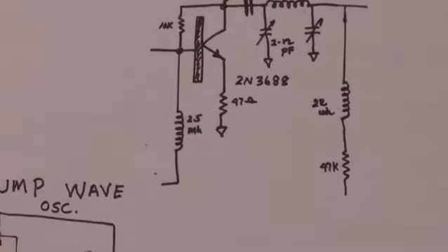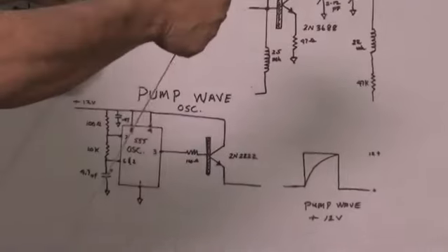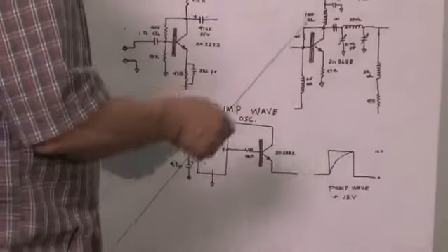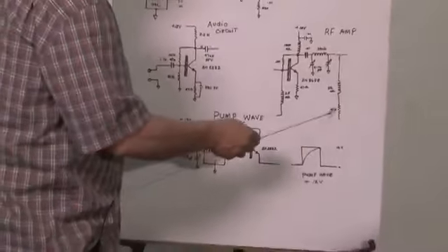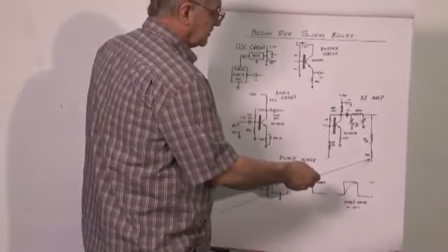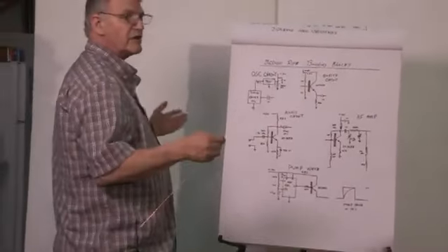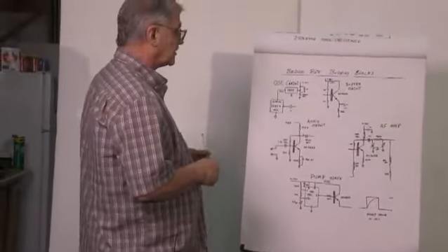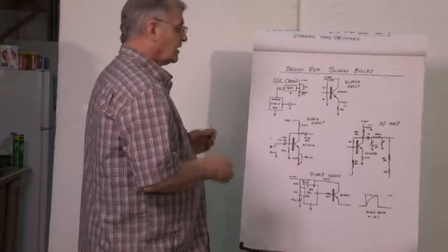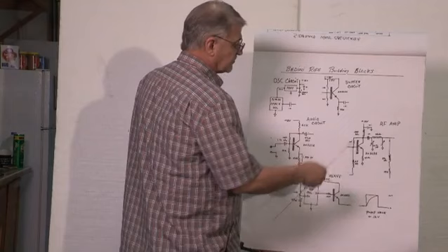That's also selected for minimum, so that when you touch it, you're in resonance. The 47K resistor limits the current that can go through your body, because you only want 2 milliamps or 3 milliamps. You don't want anything more than that, because the DC is what allows the frequency to get in.